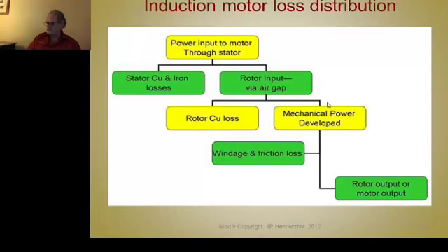In the case of these induction generators that are used for wind turbines, you have 3 slip rings and multiple sets of copper graphite brushes, which act like little friction brakes on the shaft. So you have losses from that.